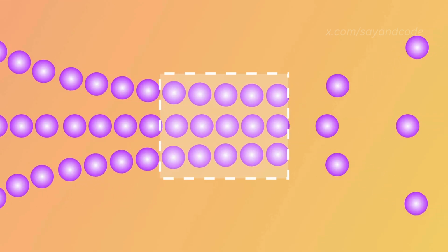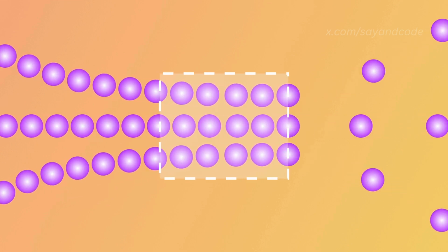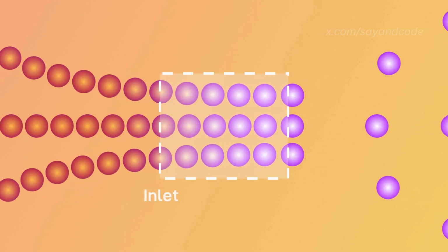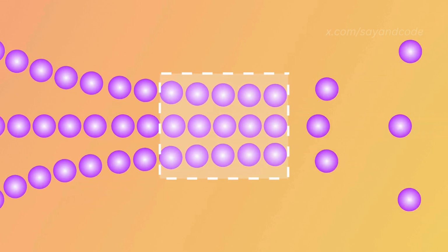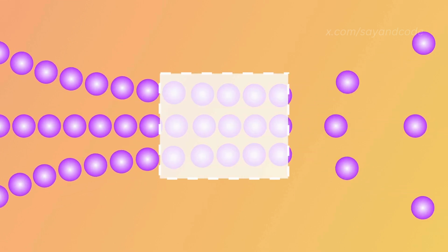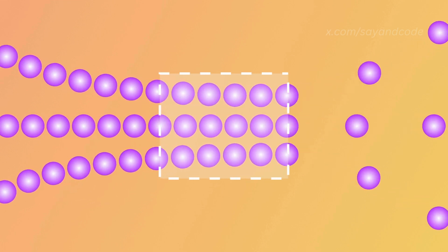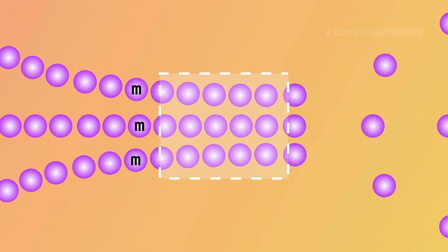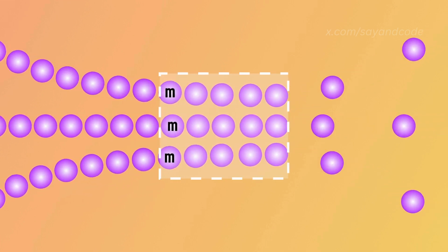In open systems, there is a flow of matter through the boundary. Sometimes, we like to compare the matter that is coming into the system through the inlet with the matter that goes out of the system through the exit. This helps us to understand how our system has affected the matter. Steady flow process is one type of open system in which the quantity of matter or mass coming in and going out of the system remains steady or stable.